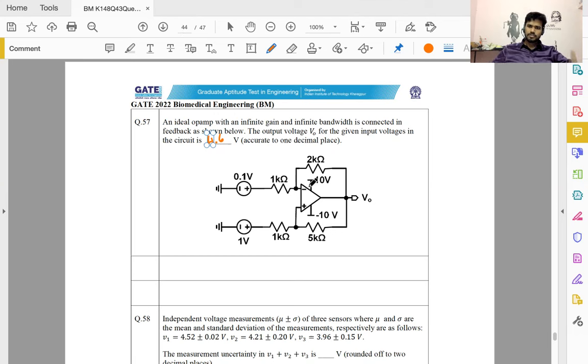Regarding that, I had put a solution discussion of the 2021 paper. There I specifically mentioned this issue. Notice there are 2 feedback loops. Now the issue is what is dominant, is the negative feedback dominant. Things are in the linear range and all that matters. So in this case, assume linear, see if there is a contradiction, see if V0 goes to saturation. If you assume linear, you can use all the rules of op amps. Solve for this. Let's say this is V. Let's say virtual shorting holds good because it's in the linear range.